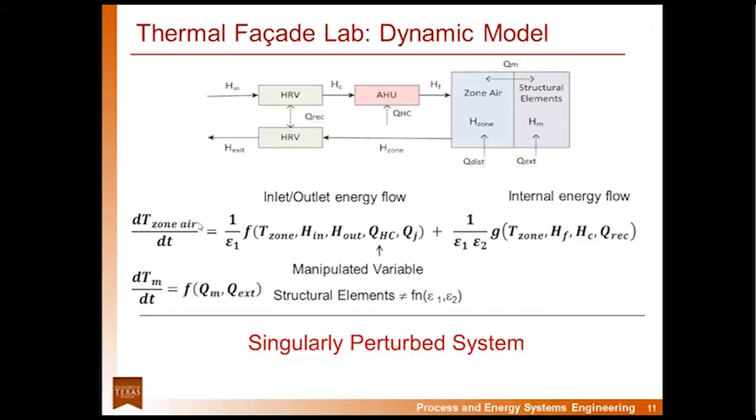Well, let me address the first question, and then if something else comes in on the chat pipeline, we can take those questions. So commercial buildings are a little easier to modulate because cooling is done at an external chiller station, and then the zones themselves are cooled with cold water. So the same tenets would apply, but you have a little more in terms of degrees of freedom. You also have a little more in terms of disturbances, because occupancy varies more significantly during the day.